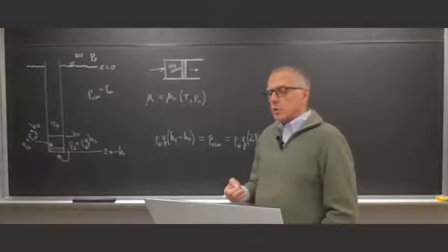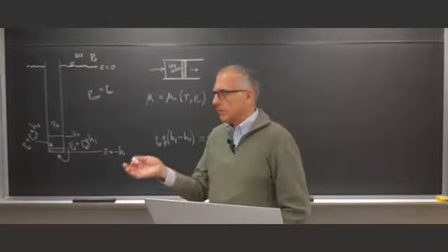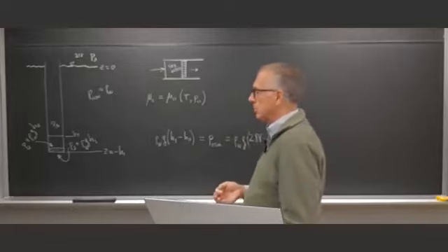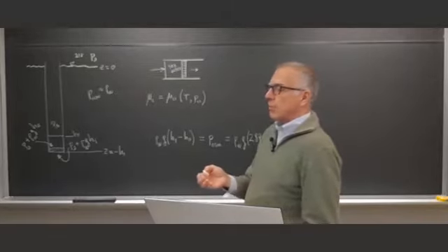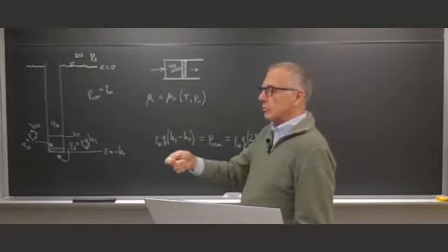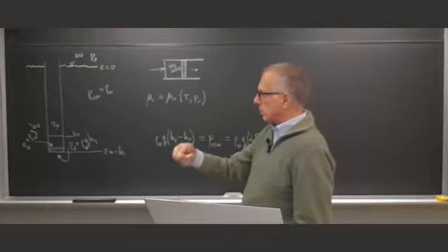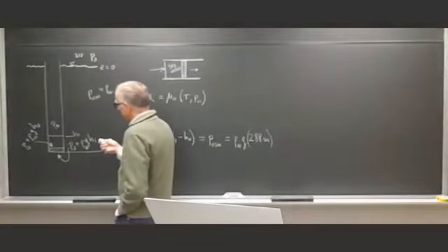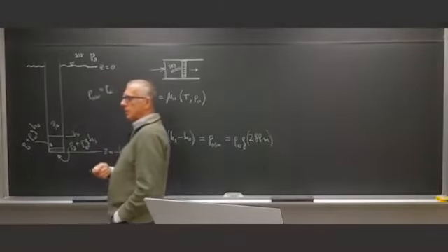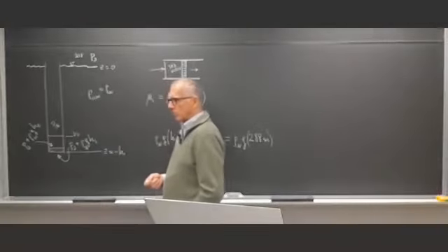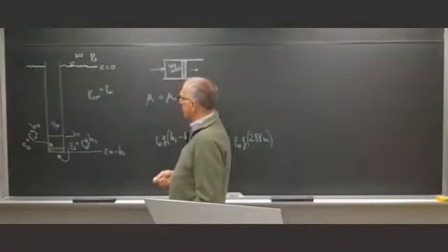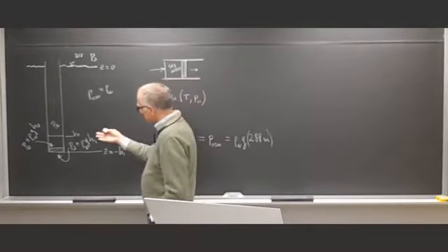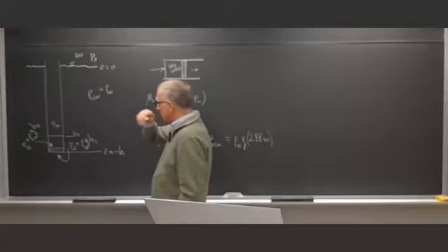Each of these methods has an efficiency, and if we are talking about second law efficiency, like we like to do in this course, you'd have to compare what you spend with the minimum you could have spent. And so what is the minimum that we need to spend in order to produce 1 liter, or 1 kilogram, of fresh water? Well, you have it in front here.